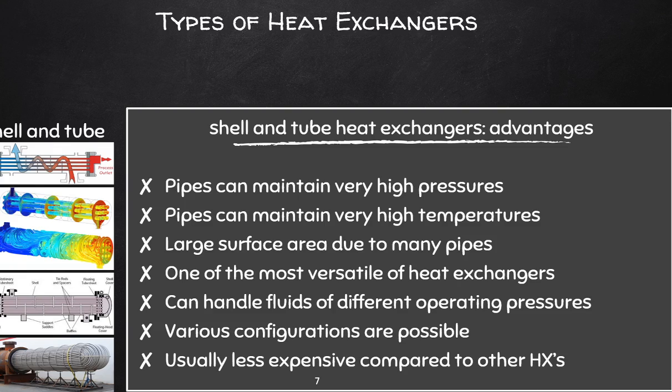The configuration of piping achieves a larger surface area than just a double pipe heat exchanger, with a small volume of space utilized because you can stack the pipes, and the pipes are then set in place by what are known as baffles, and the baffles then help for fluid flow through the shell side. It also has a very good mechanical layout.